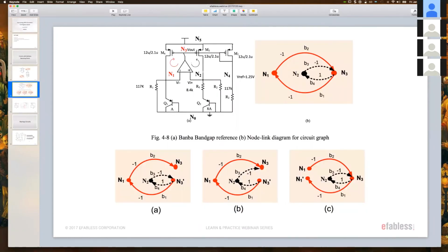Back to something like this, there is another example that was used. It was a different approach where multiple loops were used, where you're using a high gain stage to control the accuracy of the voltages across the mirror here and the transistors here, so you will have multiple loops. You're going to have a loop here and a loop here. Breaking the loop is also going to be interesting: which one to break, and if you have more than one loop in the same direction, which one is dominant.